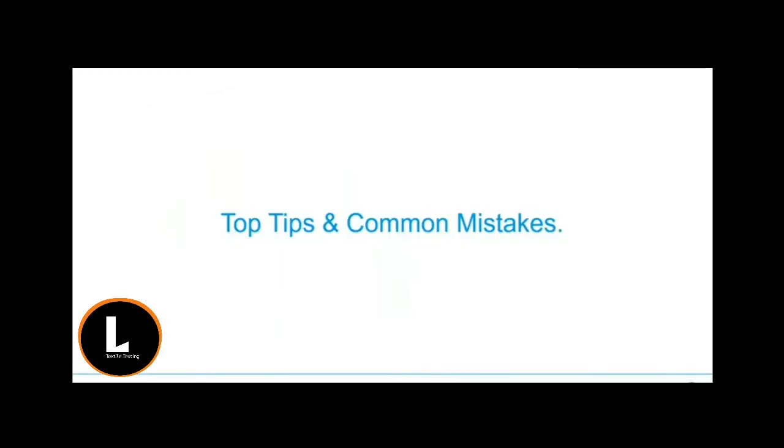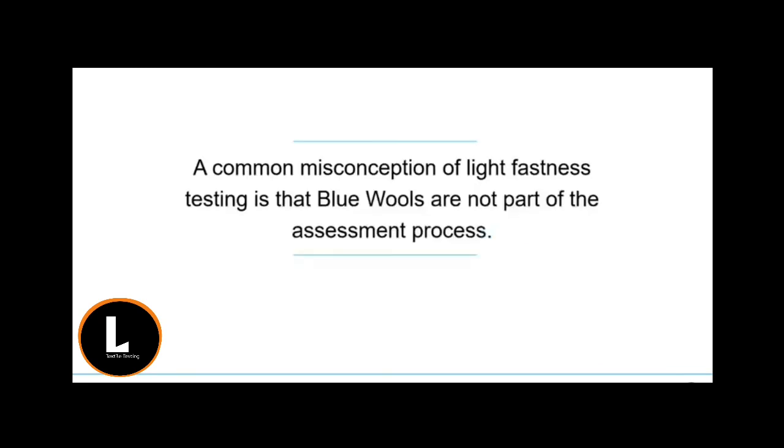So, as you might be aware, our technical team run a support desk to help with testing issues, and we often see the following common issues cropping up with light fastness testing. A common misconception is that the blue wools are not a part of the assessment process. In fact, as you have seen from the testing examples we have run through, the blue wools are an integral part of the test.